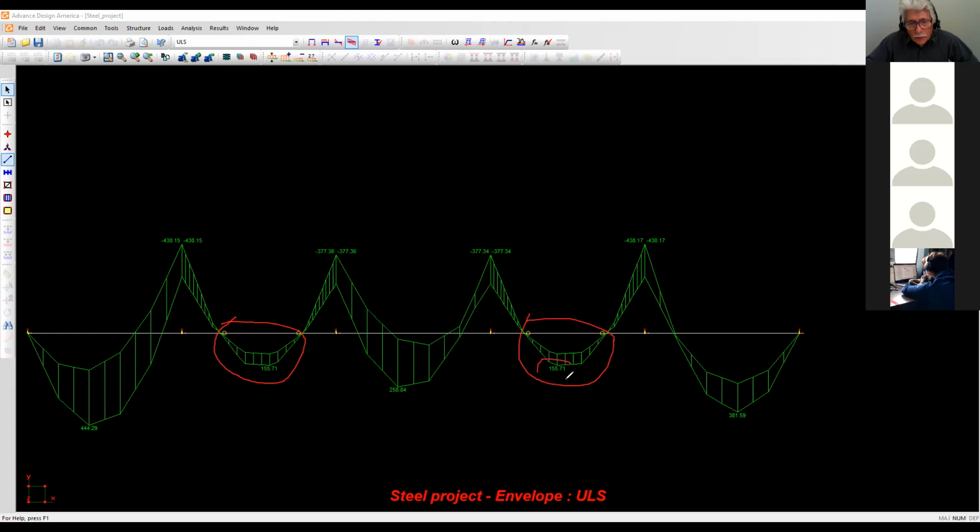What's the MF value? 155.71. It's a little bit less than the other one because the other one had a heavier beam, you understand? But it's in the same order of magnitude. This is what's happening. Here's my column. Here's my cantilever. And here, this is a drop-in. The drop-in is as if it's sitting on a pin, because it's a pin connection.